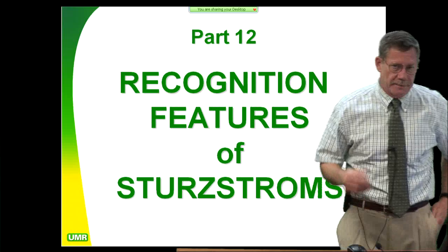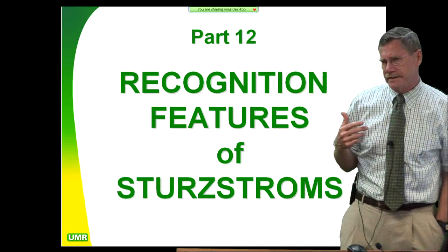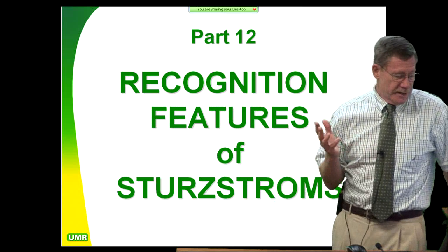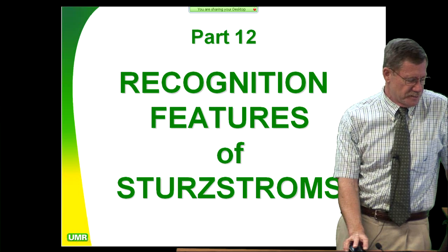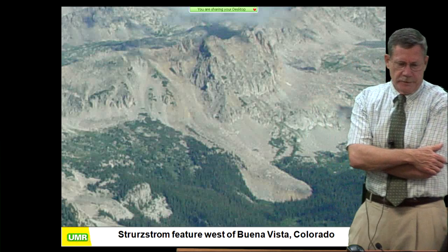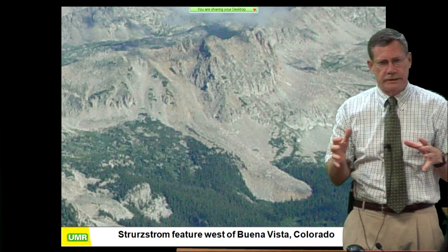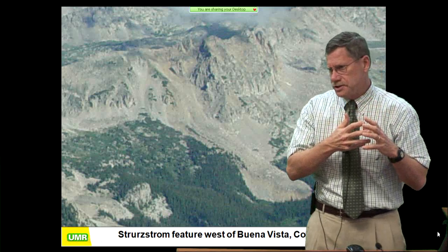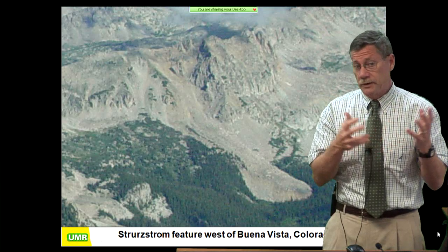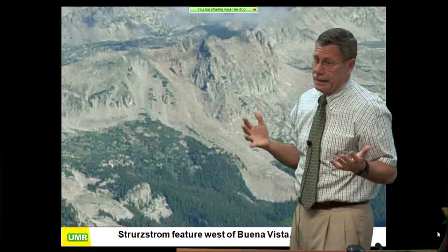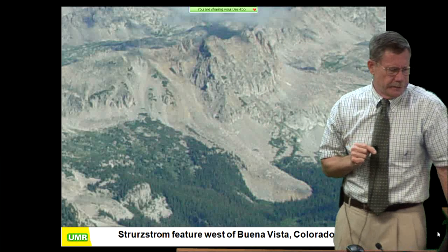Right now I'm going to give you, again, I'm trying to hit things in the lecture that aren't in most of the textbooks based on my professional experience. One of the things we didn't talk about much at all when I was in school was sturzstroms. Sturzstroms are catastrophic rock slides where you have more than 500,000 cubic meters of material and you drop it more than 150 meters, and through conservation of momentum it loses all shear strength through vibration, even though it's dry, and it behaves like a fluid until it flows far enough and dissipates enough energy that it suddenly sets up, just like concrete. So sturzstroms are a very real problem.